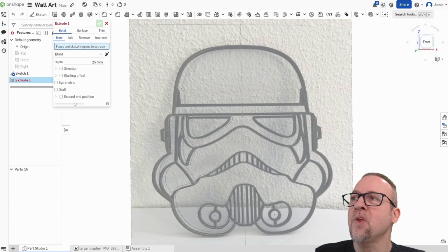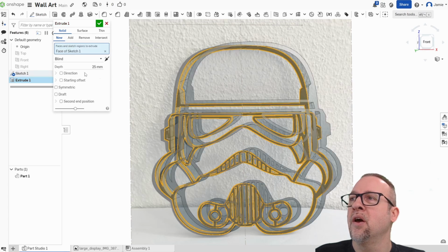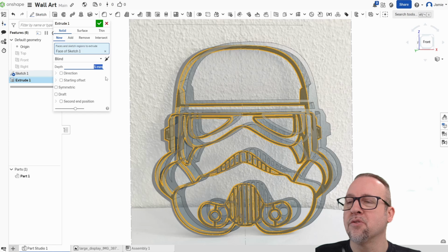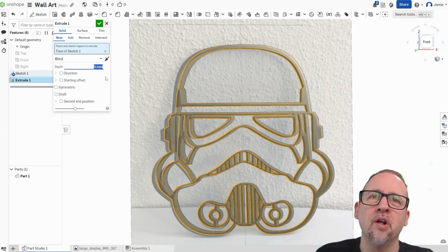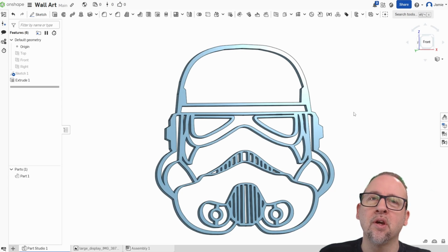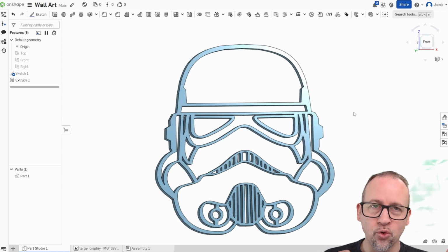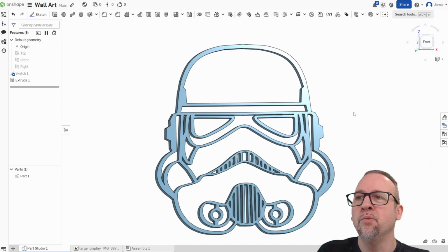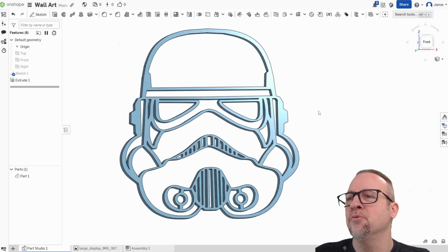We're going to create a new extrusion. We're going to click on that guy, and then we're going to move it to 5 millimeters. I said before we'd like to run it about 5 millimeters, and that will reprint it at 5 millimeters. And then we can have a good representation of what it would really be like. And I think actually 5 millimeters might be thick enough.